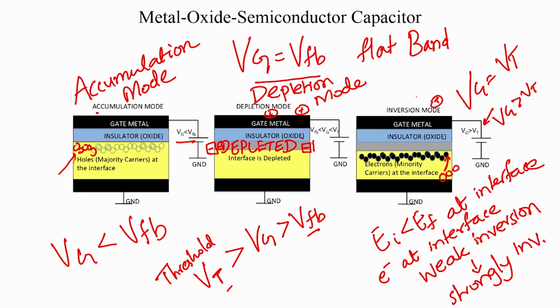all the excess positive charge in the gate is now mostly compensated by the electrons rushing to the interface and not so much by the depletion charge. So, the depletion width stops increasing. So, this is the story. Initially you had flat band, when you start making Vg greater than flat band, the first thing that happens is that the depletion width